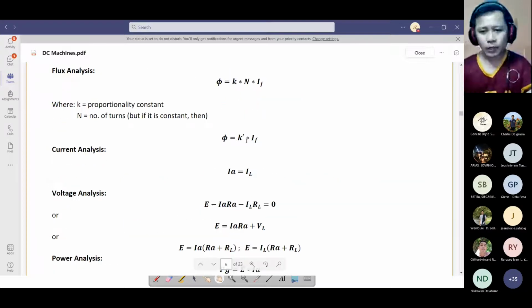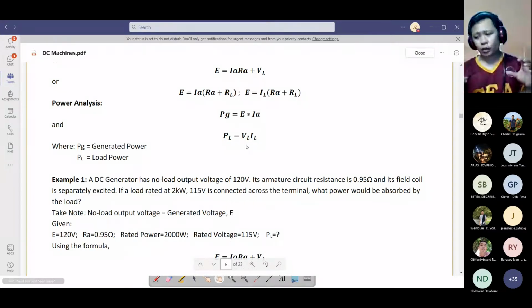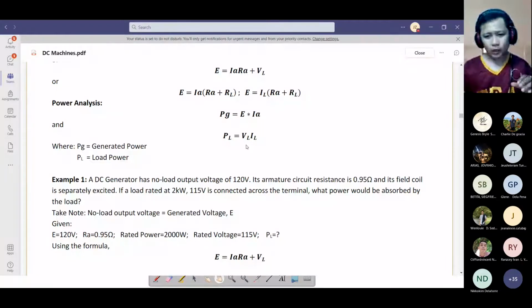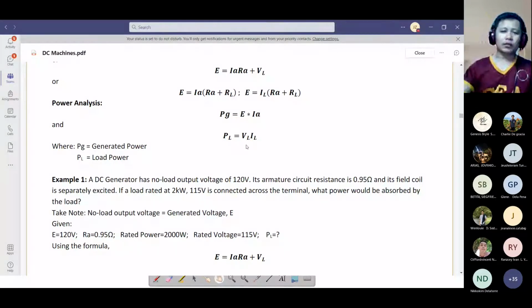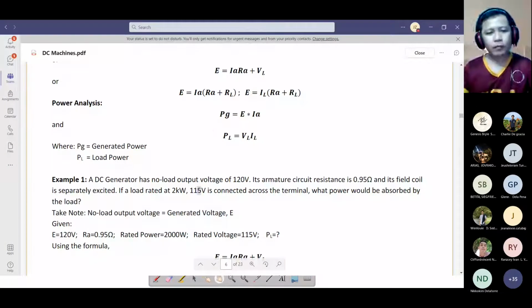Because usually, when you connect loads, your electric fan, TV, charger, aircon, laptop, they are all connected in parallel. And if they are all connected in parallel, take note that the characteristic of a parallel circuit is equal voltage no matter how many parallel connections there are. So technically or theoretically, your 115 volts load voltage will remain the same. But why theoretically, sir? In actual, sir.